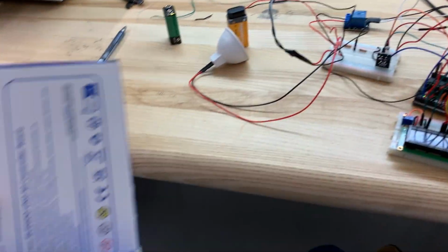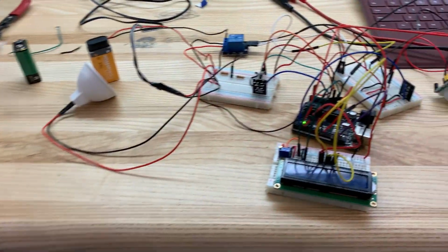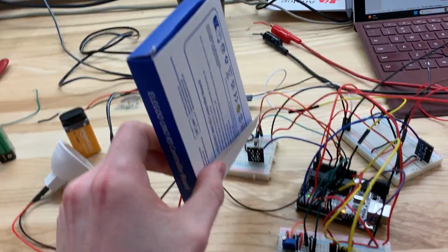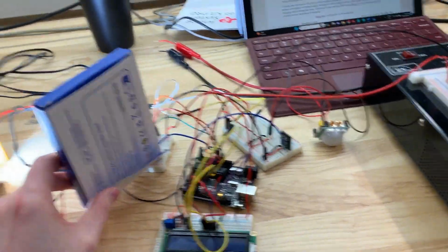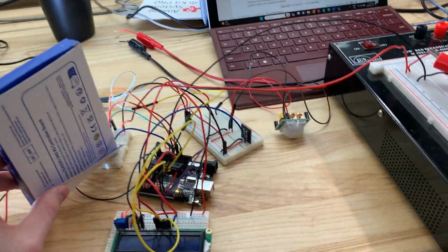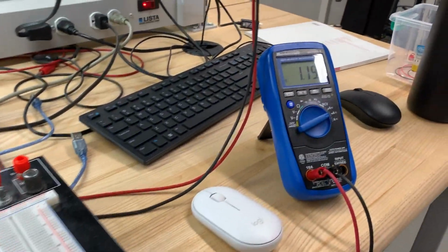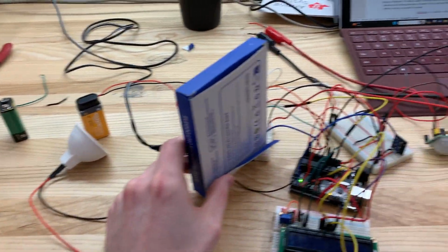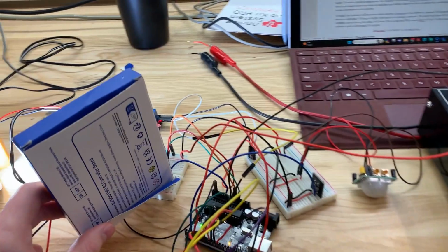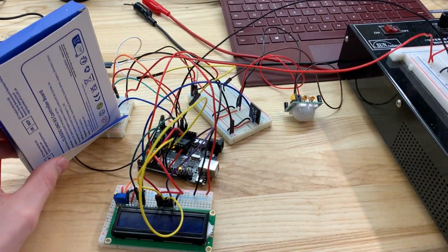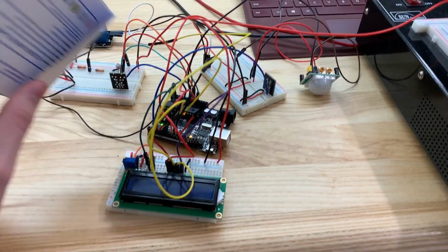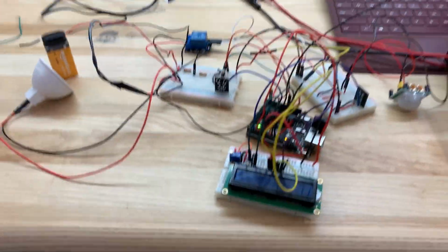As you can see here in this video, I managed to successfully get this working. In the light, the circuit worked as expected, and then by covering the light-dependent resistor, my motion behind the camera triggers the motion sensor and flips the relay, turning the lights on. As you saw here, I also measured how much current my Arduino is pulling in its different operating modes to understand the power consumption compared to what I had expected, which was lower than expected by about a factor of 10 with the help of low power mode.